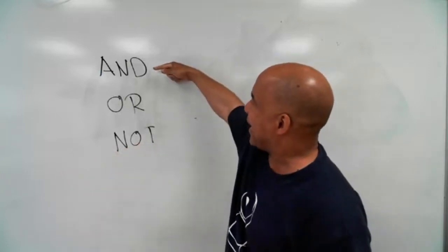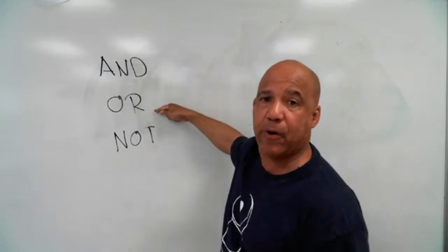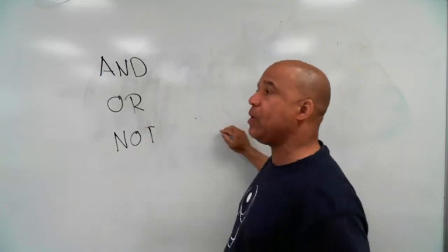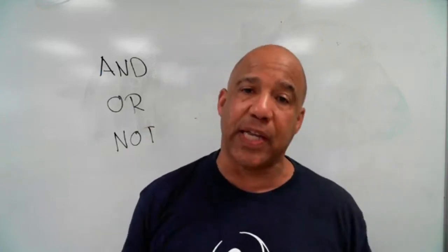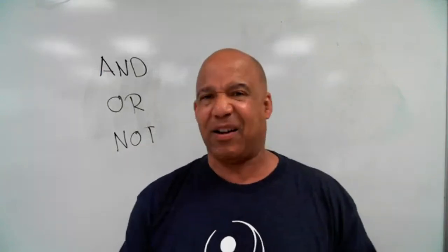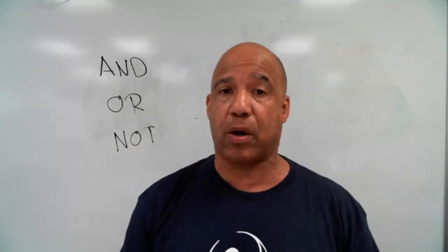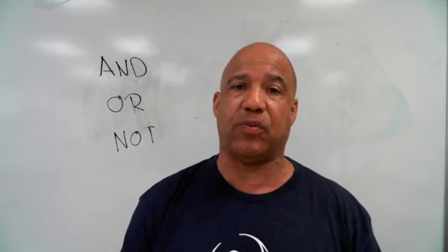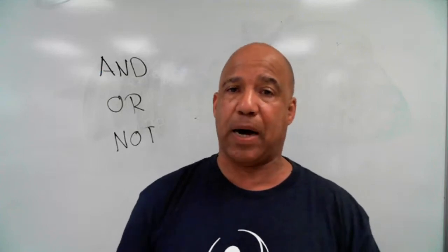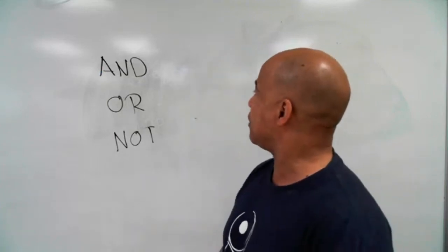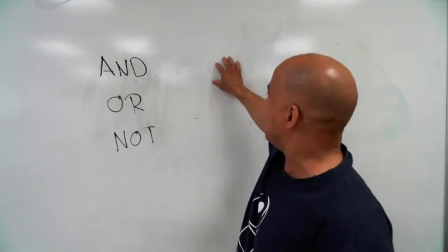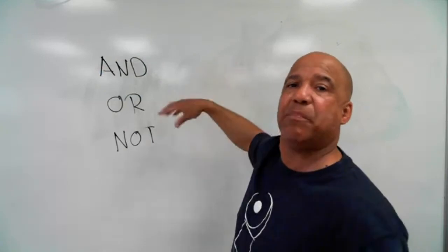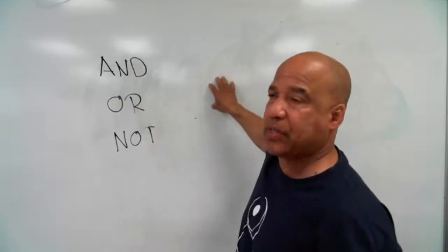Now remember, when I went from the AND logic to the OR logic, I had to go in and rewire those switches. I had to go from series to parallel. The other thing we talked about in the last class was a relay. I showed you a picture of a relay, and we talked about how relays work. You'll do your first quiz assignment. It's going to deal with relays. You're going to watch a video, and then you'll talk about what you learned in the video as to do with relays. So even though I'm showing switches in series and buttons, really we're doing the same thing with relay contacts, but it's easier to think of them in terms of switches.